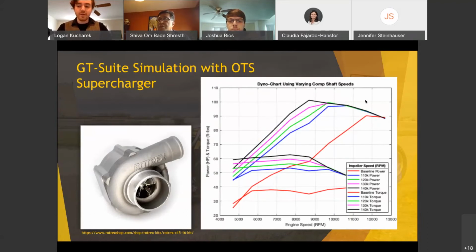As impeller shaft speed was increased, peak power increased while also shifting lower into the RPM range. Each increase in impeller RPM predictably raised peak horsepower by 3 or 4, with the largest horsepower examined to be 101.16 horsepower. Most impressively, the torque curve showed the desirable flat lines across most of the RPM range of the engine, while still providing an excellent raise in peak torque.